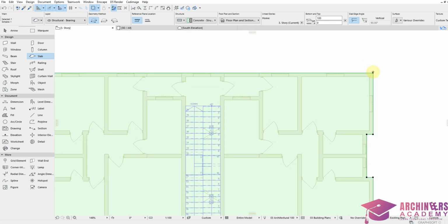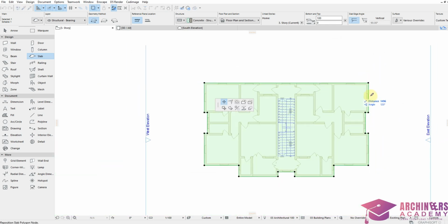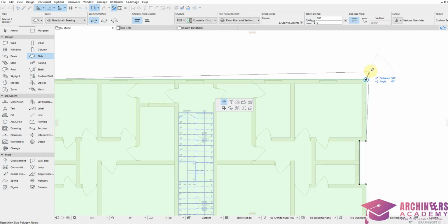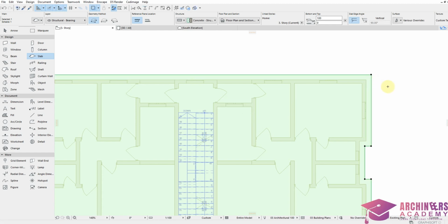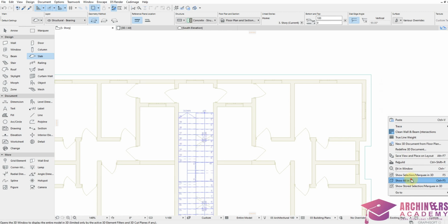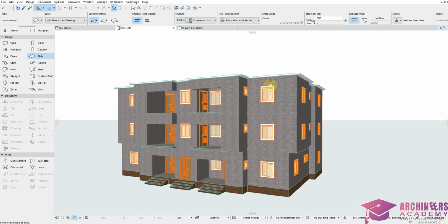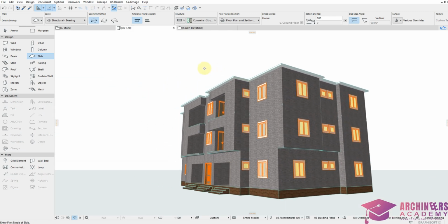So now we will offset it, because roofing has an offset. Since we are using concrete fascia, we will offset using concrete fascia. Once you pick an edge, any of these black dots, this dialog shows. Then you click on offset all edges. Then you can offset by maybe 300, because this is the first offset. You can also confirm what you have done. So this is what we have done.